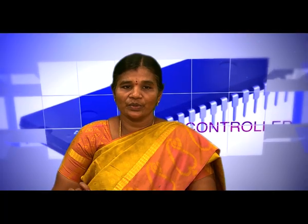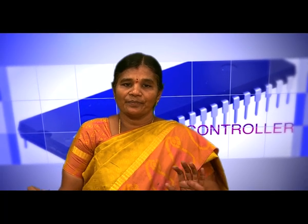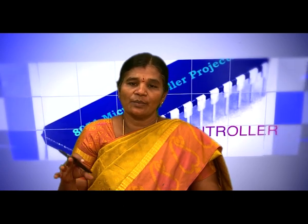Now we will discuss the next program, which is used to receive data. Write a program for the 8051 to receive bytes of serial data and display them in P2, that is port 2, with a baud rate of 2400, with SCON set for 8-bit data, receiving with a single stop bit. In the frame formation, data of 8 bits is sent along with the start and stop bits. The start bit should be 1, and you can add more than 1 stop bit. That is why here we specify 1 stop bit in mode 1.